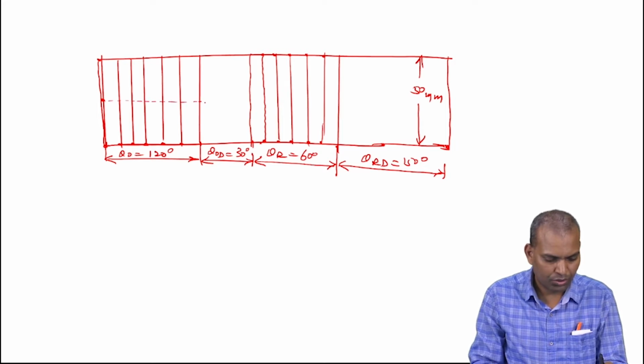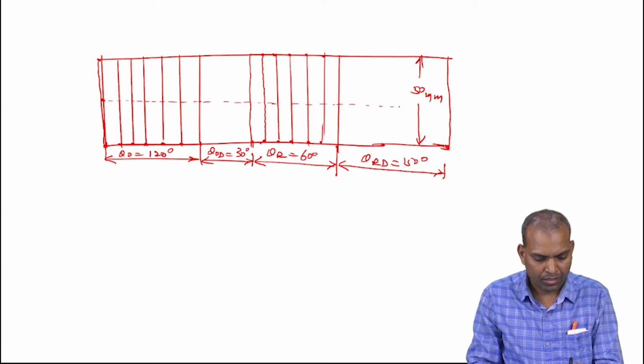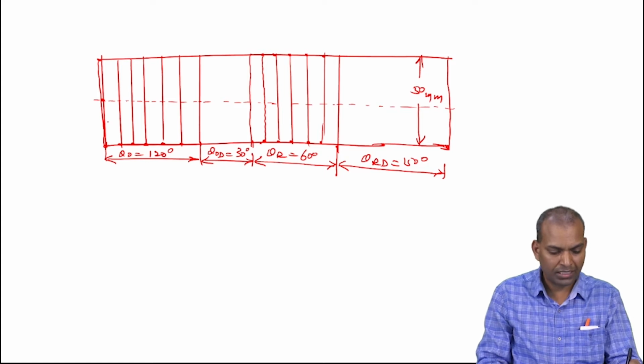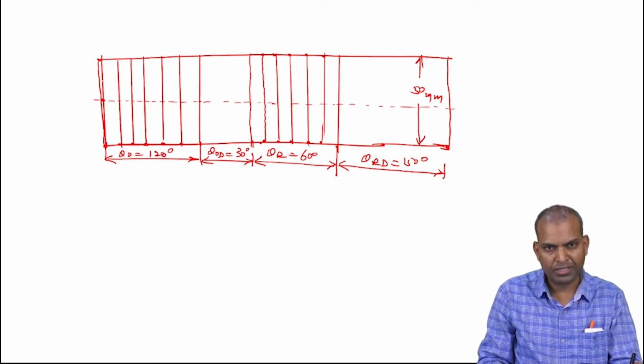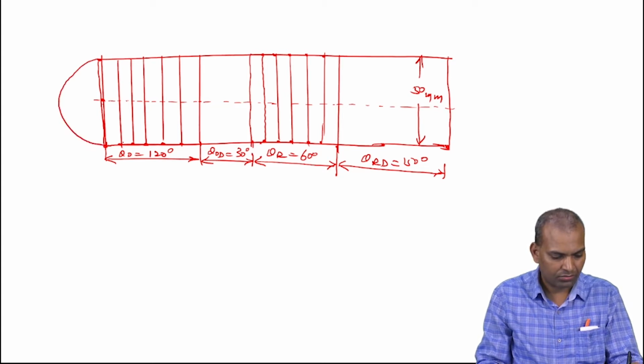This is the simple harmonic motion displacement diagram we are drawing. So draw a center line. After making the center line, with the help of the compass, take a 25 millimeter radius and draw a circular arc.